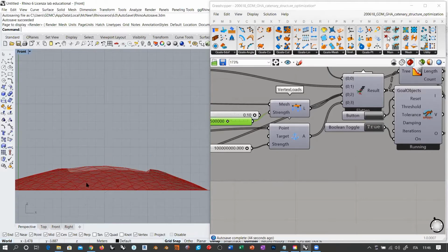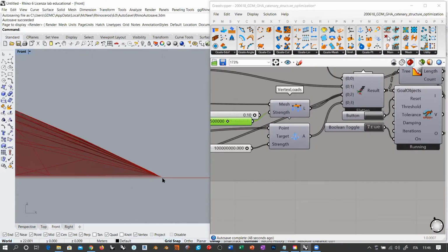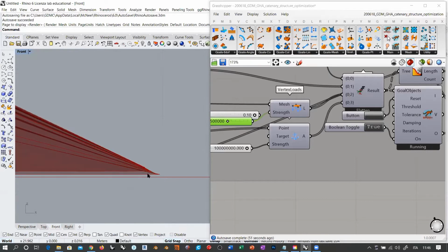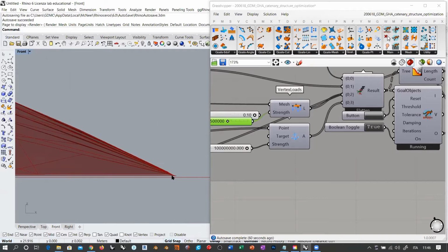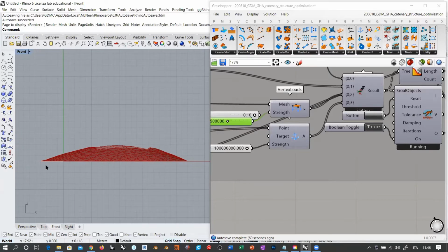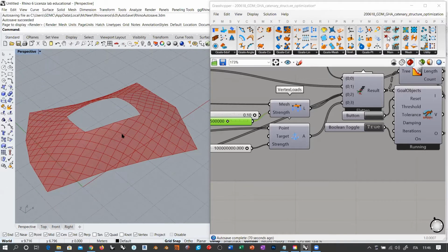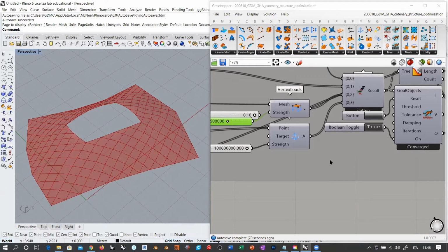Okay, and also you must double check that you don't have a displacement for the anchor points. You see that this object has already lifted up a little at the corner and around the edge, the border, because the anchor points are not strong enough. Okay, you can also, let's say, omit this kind of observation, because normally it's not that evident. But you must take this into account if you want a realistic behavior for your system.